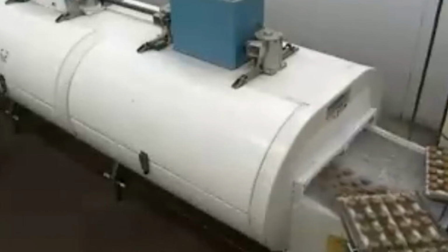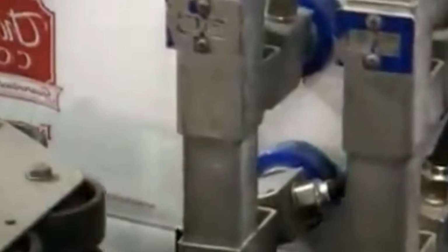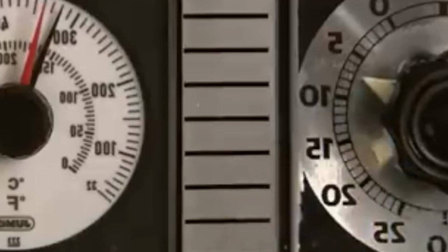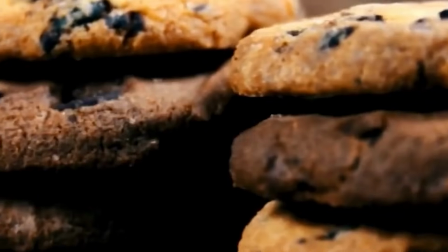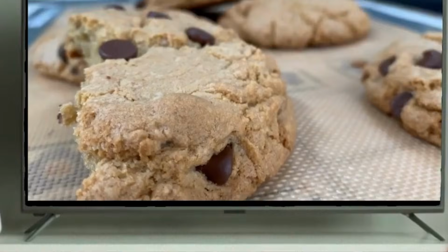The formed dough pieces move directly into a multi-zone continuous baking oven. The oven band is typically a steel mesh or solid band, depending on desired bottom texture. The oven is divided into several independently controlled thermal zones, with temperatures ranging from 180 degrees C to 230 degrees C. Baking duration is precisely set, typically between 6 to 10 minutes.